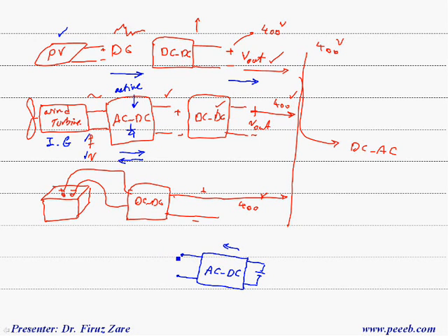In this case, if we have an inductor and if we control this current, and if we control the magnitude of current here, that means we can control the power. So with respect to this terminal at any phase angle, it's possible to control the active and reactive power.